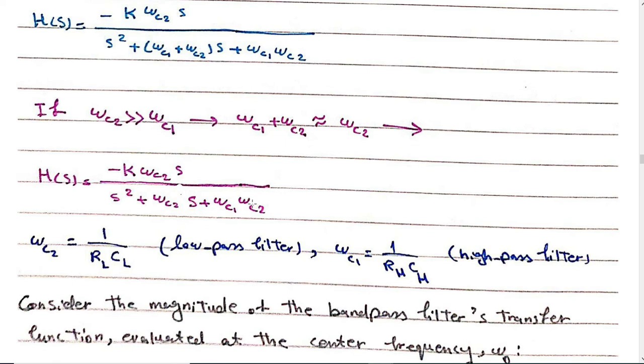But you remember in ECED 2001, if you find the midpoint of two numbers, for example between 2 and 12, you say 2 plus 12 divided by 2. But over here, I said no, you cannot. You find the midpoint for the filter by taking the square root of the higher frequency multiplied by the lower frequency. Remember?